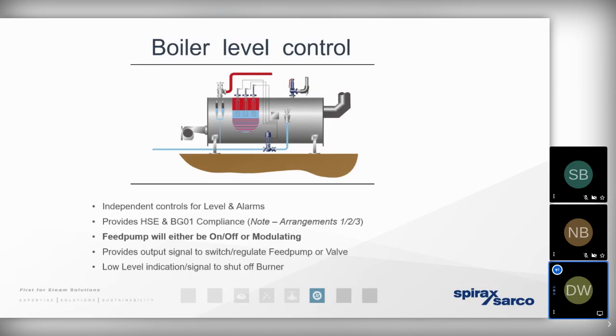So it's far, far better to move towards a capacitance level control pump for the simple reason that that is capable of sending a signal to a modulating pump. So by constantly drip feeding in a very small mass of high temperature water, we can keep the steam in equilibrium with the process demands. We're producing steam not only responsively and efficiently from an energy perspective, it means we're getting a consistently drier and better condition of steam being produced.